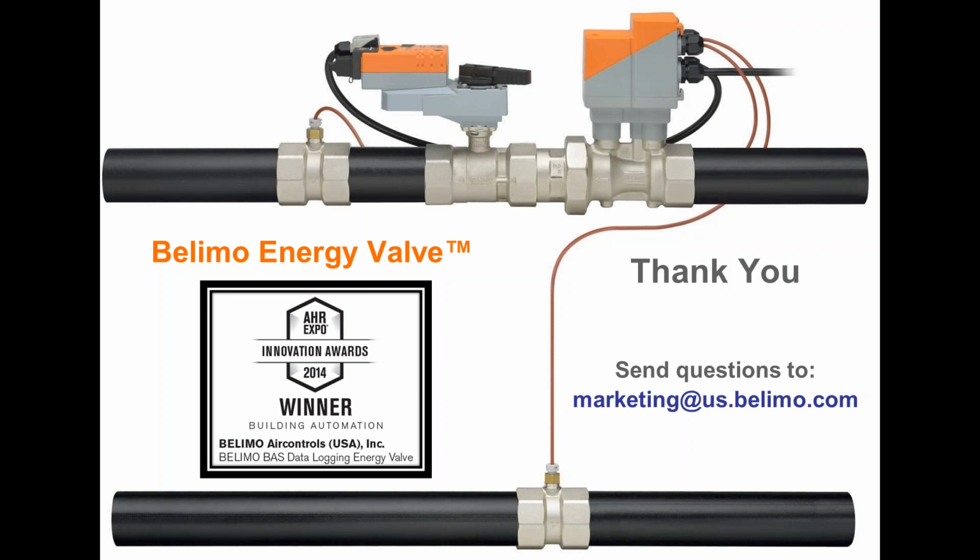First part of that question is it can be programmed two different ways, well, three different ways actually. We have a little handheld device called the ZTH that can plug directly into this. You can also plug a laptop directly into the Belimo Energy Valve. There is a Cat5 plug on the back side, and the actuator has a contained web server. So it has an IP address, and you can basically log into the actuator and program all your parameters. Most of those parameters can also be programmed directly through BACnet, so you could do that through your automation system.